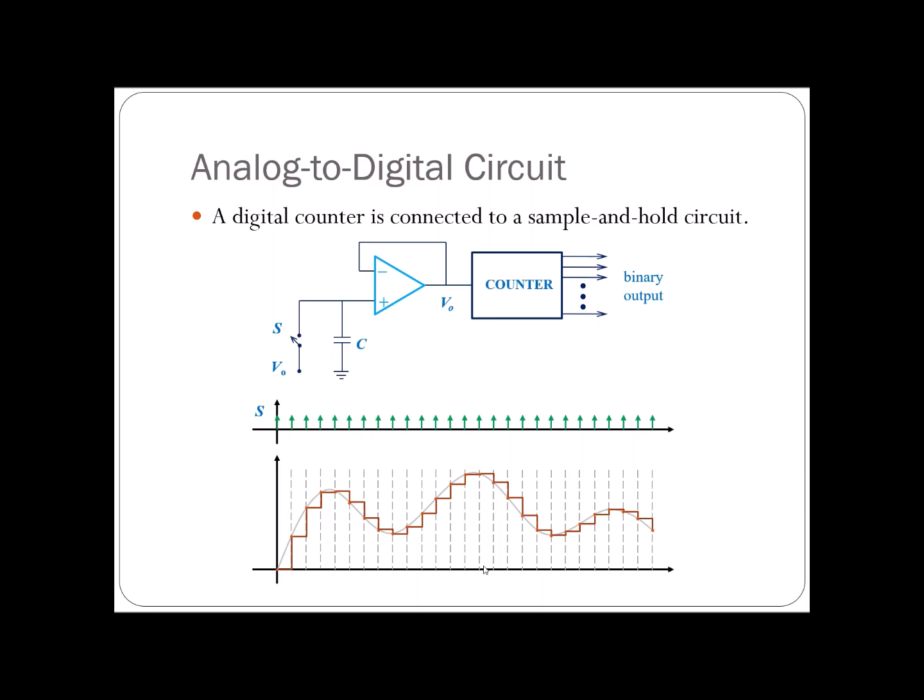It's because, same like before, I regulate the switch S, but I regulate it in this following manner. I just keep it on for a very short time and then let it off for a certain period of time. That I do iteratively. So this is how we sample it in time, but this is not the end of the story of this digitalization of an analog signal.